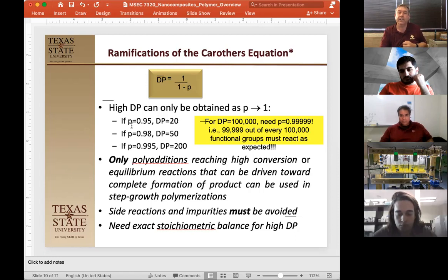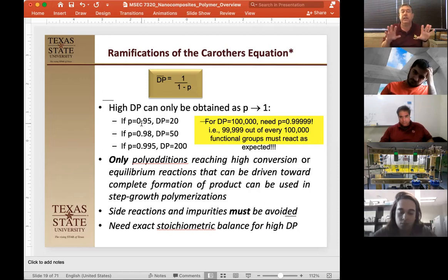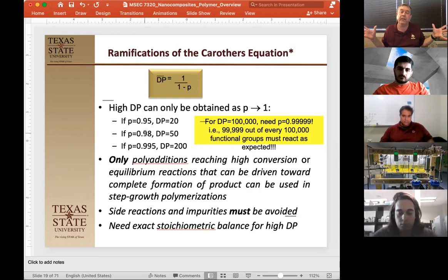So I actually have to use a degree of polymerization of 20, which means I have a ratio of 100 to 95 for my monomers to make sure that my polymerization does not get too high a molecular weight. If I change that from 95% of one monomer to one monomer, to 98% of one monomer to one monomer, that would give me a DP of 50, and that would gel out. Okay, so that works in that system.